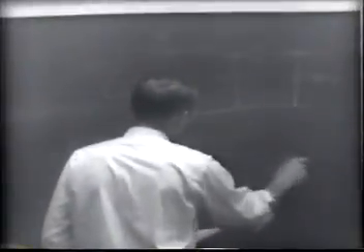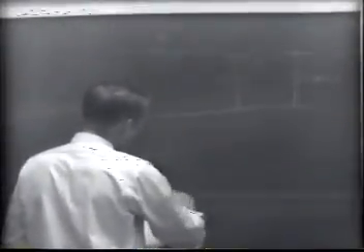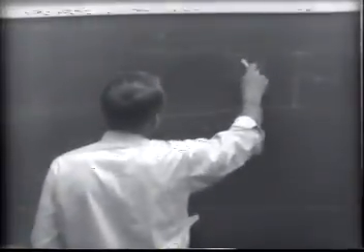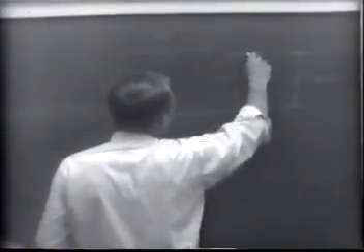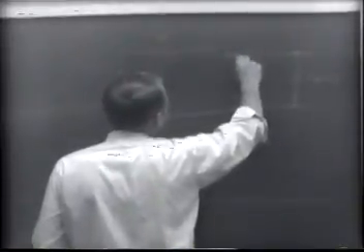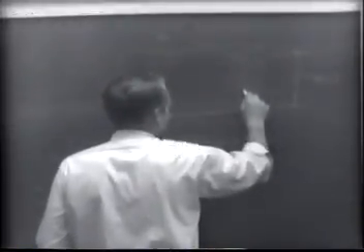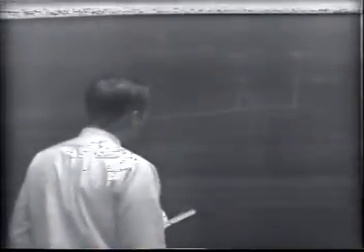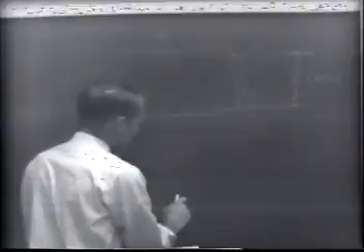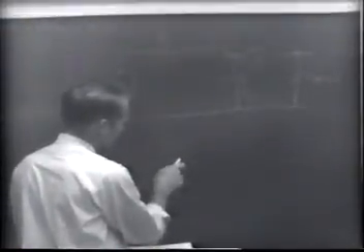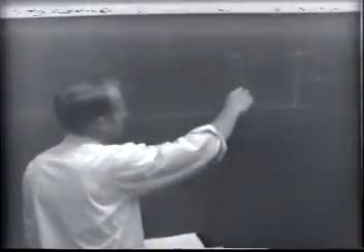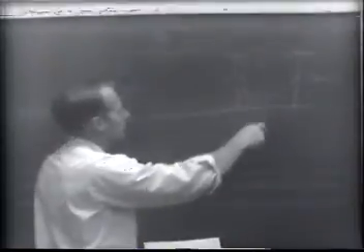this is going to be the voltage here across this capacitor. Voltage across that capacitor, as long as the circuit breaker is closed, with this closed down here, is going to follow the normal sine wave. Well, suppose just at this particular instant we have a fault. In that case, the fault with these two points shorted together is going to drop the voltage across this capacitor to zero.